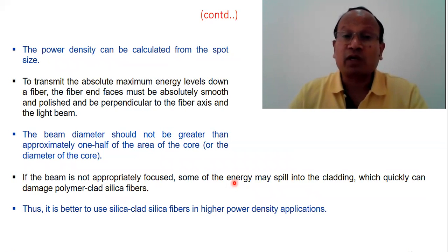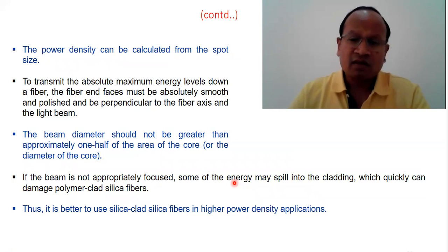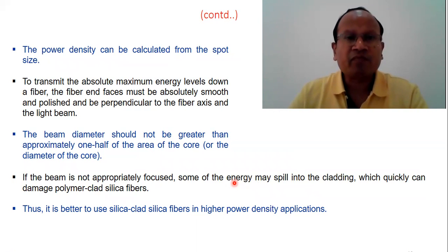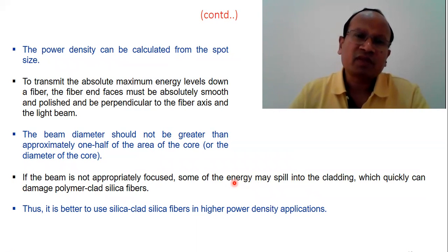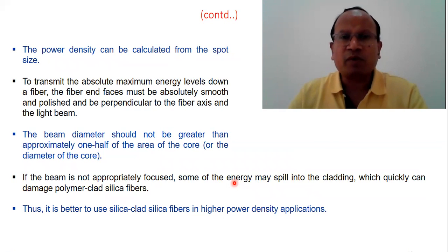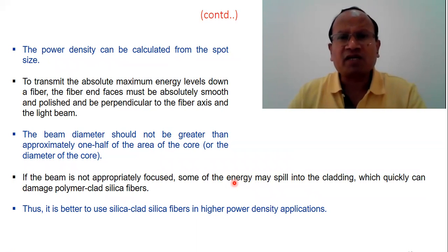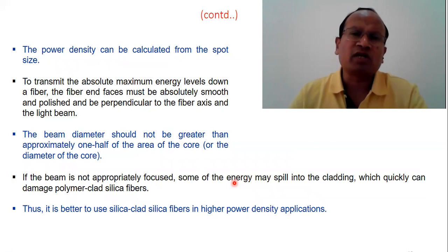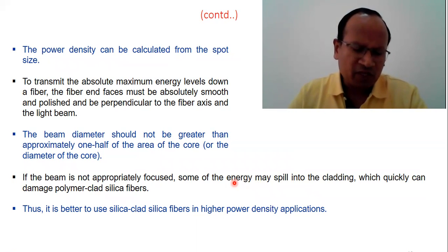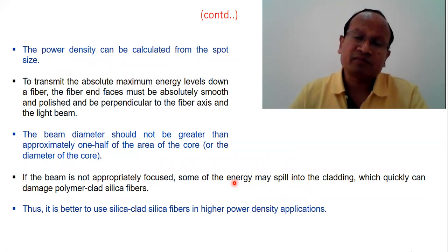But in this lecture, we have focused on dispersion losses, and that is mainly of three types: modal dispersion, waveguide dispersion, and chromatic dispersion. In all the dispersions, the thing which happens as a dispersion loss is that the pulse is broadened.